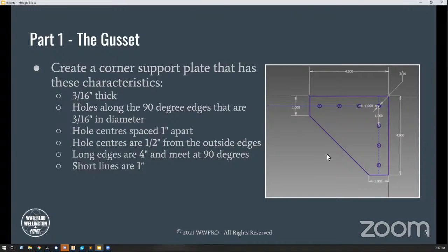And then I'm going to open it up for questions or any other things, questions on anything that I've done so far, or on how to get constraints to work. Your goal here is to get this fully constrained. And as a hint, what I've done here is I've set this corner in the upper left-hand corner of this part to be locked to origin. So there's a little hint for you for how to lock the thing in.